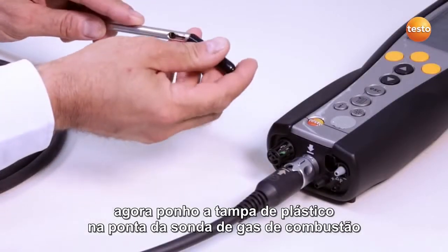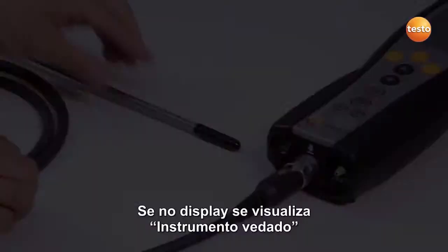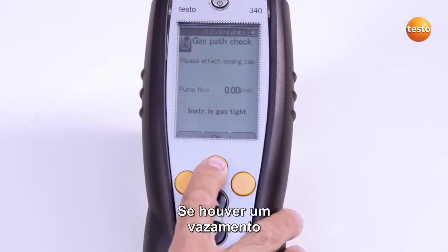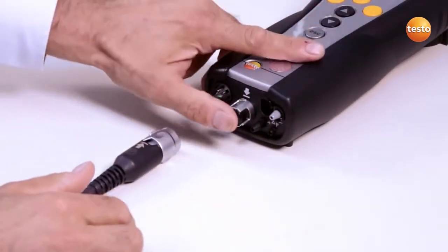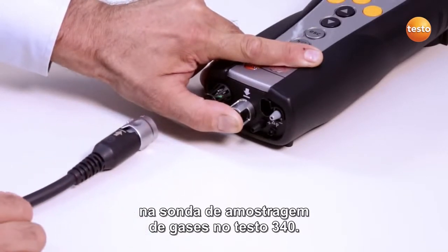Now I put the plastic cap on the tip of the flue gas probe so that its opening is completely covered. If Instrument is gas tight appears on the display, I can finish the test by pressing OK. If there is a leak, you can seal the gas inlet using your thumb and carry out the gas path check again. This enables you to check whether the cause is the gas sampling probe or the Testo 340.